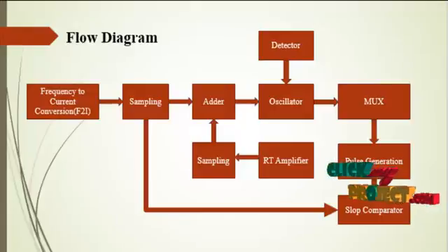The multiplexer is used to select between the clocks generated by the oscillator and detector circuit. The decision to switch between these clocks is made by the detector circuit depending on the state of the RT bar clock pin. The output of the multiplexer circuit is used by the pulse generator circuit to create a short duration pulse in response to rising edges of the selected clock.